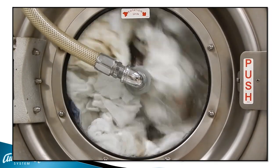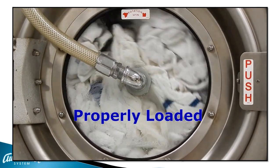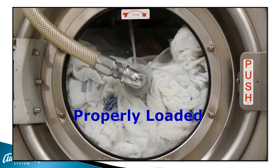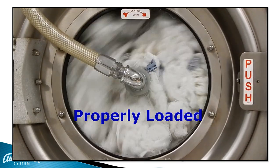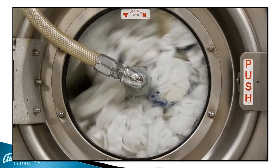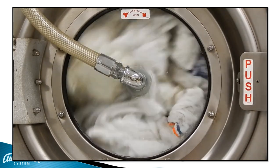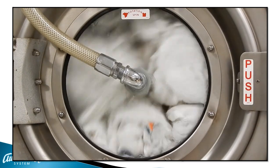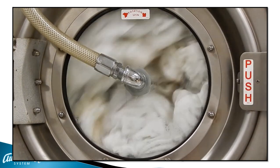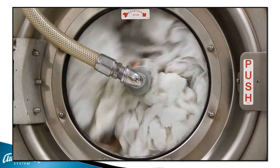Here we're looking at a washer that's properly loaded. We're getting good mechanical action. There's good distribution. And as the washer goes from forward to reverse, the linen is getting mixed up. Water, detergency, alkalinity, or bleaches are all getting mixed through the washer extremely well. This will give quality results.